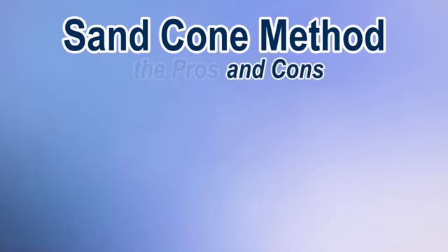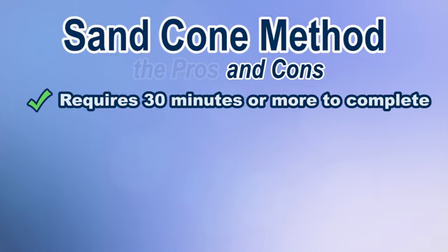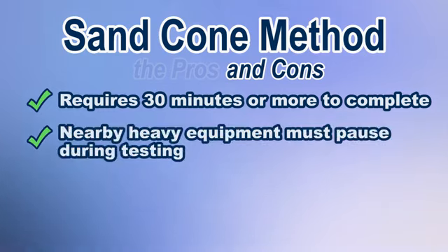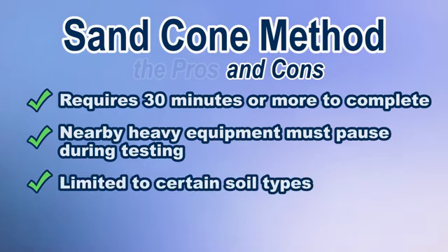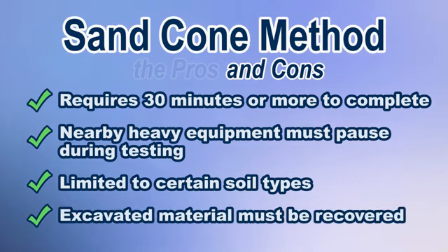The cons are that the sand cone test requires 30 minutes or more to complete. Nearby heavy equipment must pause during testing. It is generally limited to unsaturated soils, not soft or friable soils. And all excavated material must be carefully recovered for accurate testing.